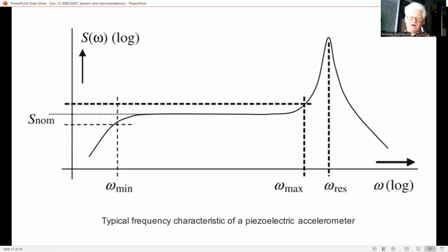A very sensitive accelerometer has been achieved to be used for very low frequencies as a replacement for a geophone. The resonance frequency, let's look at this figure, please, amounts to 265 Hz, for a particular choice of the parameters. The sensitivity in this case is almost constant up to 100 Hz.